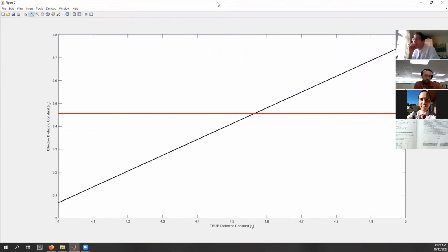Sorry, so that was a little fast. I kind of went through that quickly. Are there any questions on that? Because that's essentially what you're going to be doing with your lab. You're going to be plugging into these boards here. You're going to characterize the impedance. You're going to figure out what the propagation velocity was, and then use that to kind of reverse engineer the dielectric constant.